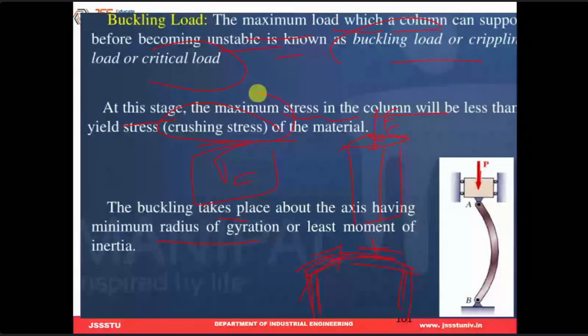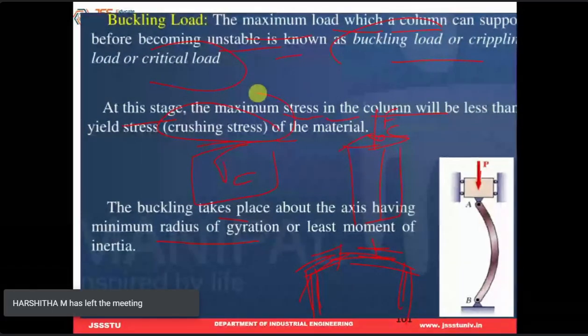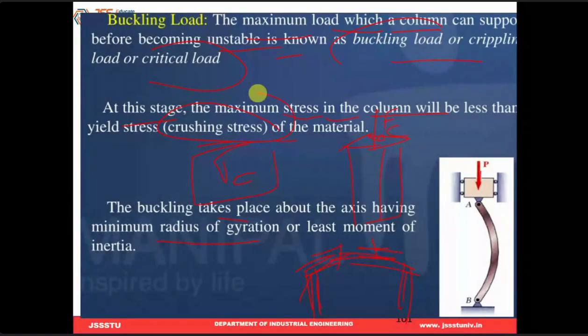So when it reaches the crushing stress, it is immediately going to break at any moment without showing any kind of sign like bending. It will suddenly crack and fail immediately. So suddenly a crack will form and it will break, because that is not ductile behavior, it's called brittle behavior. In brittle behavior, what happens is that first a crack suddenly forms and it immediately collapses.